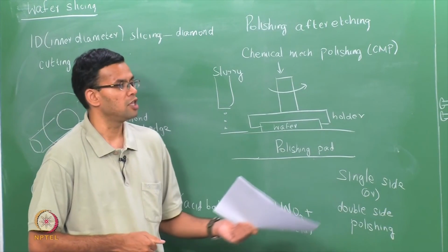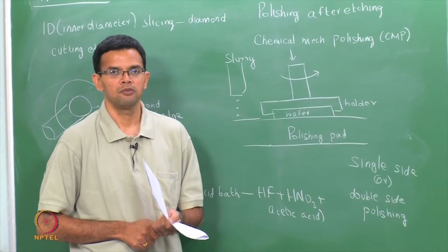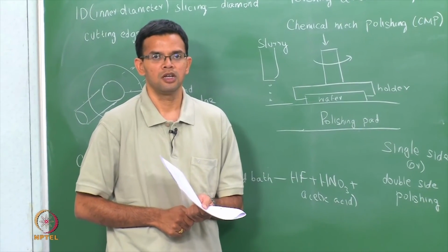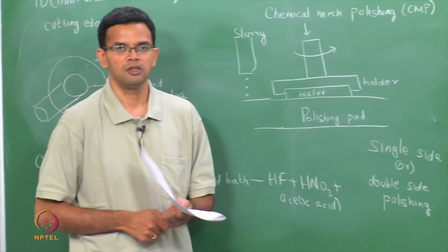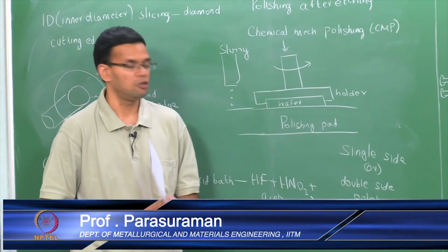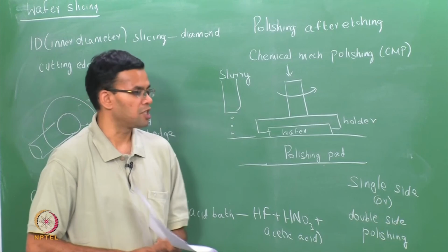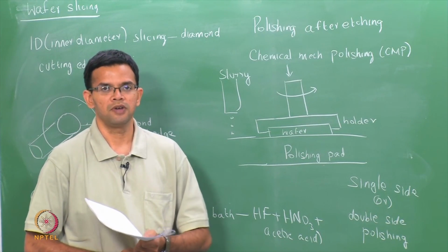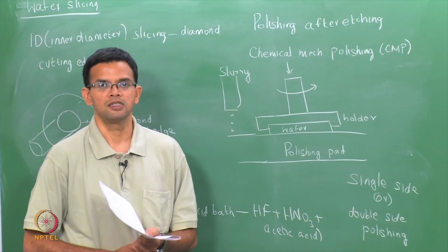We saw in the case of the operation that we did not consider the effects of doping, but you could also dope during the silicon manufacturing process in order to get doped wafers. So, some sort of electrical measurement, usually a resistivity measurement, is used in order to check the resistivity of these wafers. After inspection, these blank wafers are ready to be transferred to the fab. They will be used for the manufacture of the IC devices.